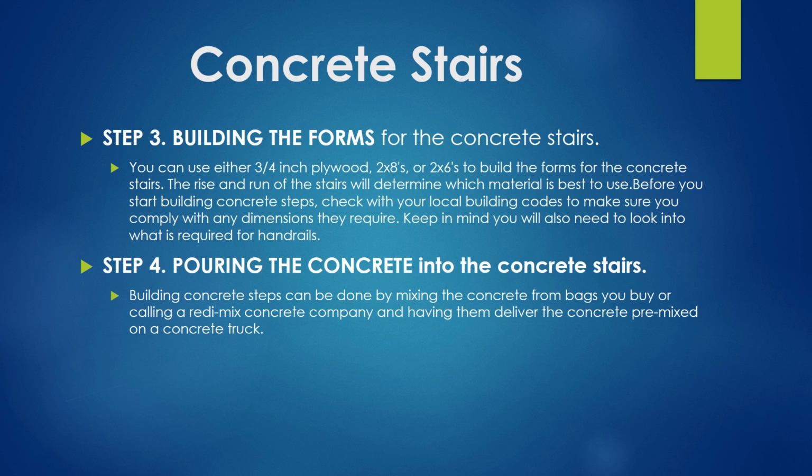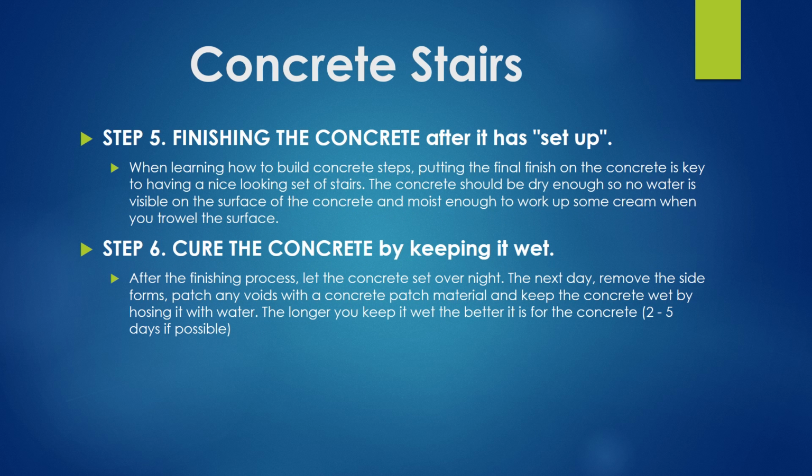Step 4 is pouring the concrete into the concrete stairs. Building concrete steps can be done by mixing the concrete bags you buy or calling a ready mix company and having them deliver the concrete pre-mixed on a concrete truck. Step 5, finishing the concrete after it has set up.